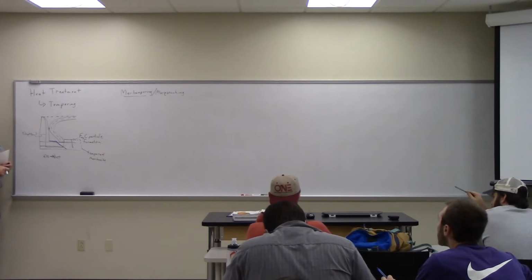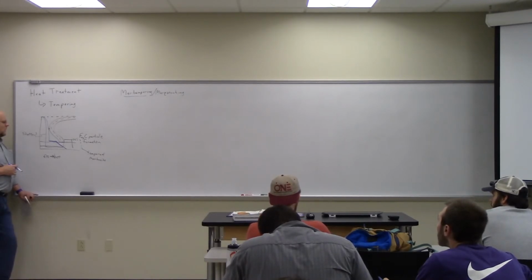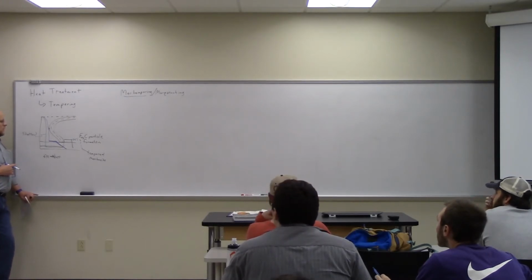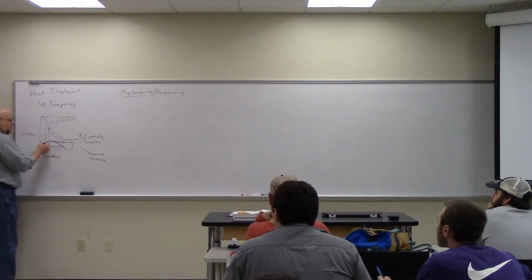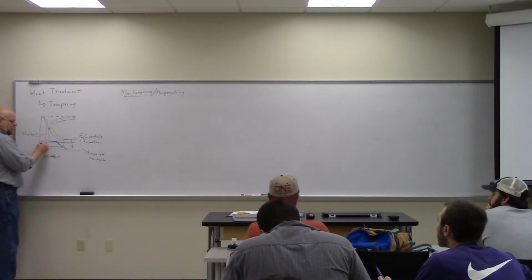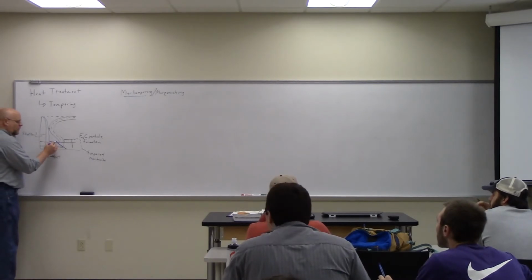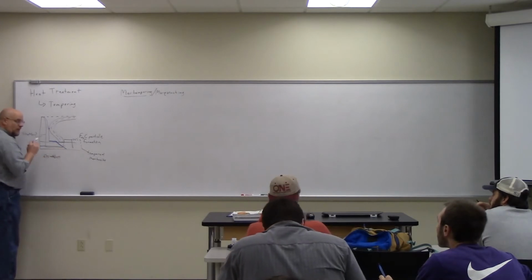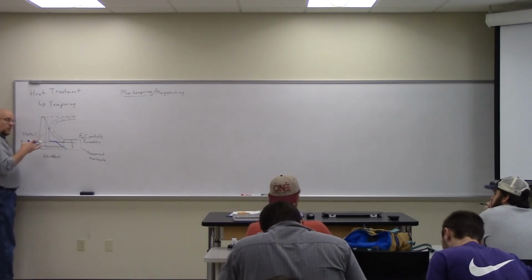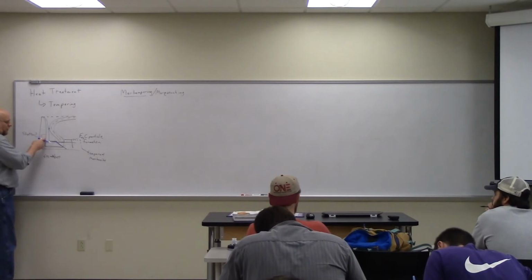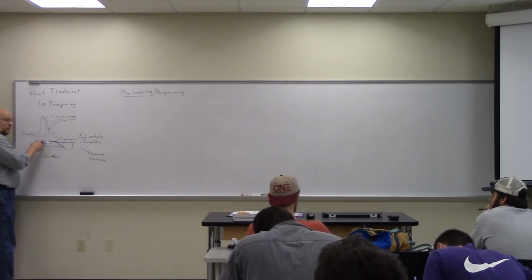So what's the advantage of that? The blue line? Yeah, besides avoiding the lines, is it just so you don't shatter the material? Yeah, it's just to avoid shattering, because you don't have any martensite formed here, right? So there's nothing to shatter until you start forming martensite. So you go through that part of the quench slowly, so that you allow things to equilibrate better, as opposed to quenching all the way down through here, so that once I start forming brittle material, now it's brittle and can shatter.